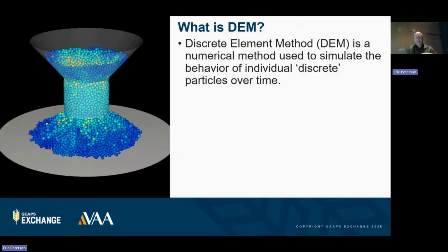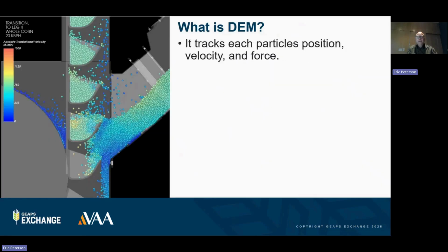So what that means is that you take a physics model and use it with specialized software, and you can have individual particles, just like kernels of grain, behave with each other and with boundaries in a way using established physics models, using forces of gravity and other things, to simulate real-world behavior and flow of materials. That's one way that it's used. So like I said, it tracks each particle position, its velocity and force.